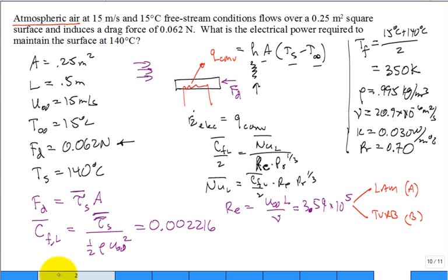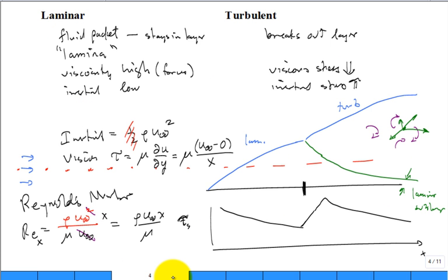So I know that I talked about this condition right here, but maybe I failed to emphasize something, but it's emphasized in the prerequisite course, right? What is the Reynolds number at which you would expect to have a transition between laminar and turbulent flow for flow over a flat plate? A lot of students will say one of two numbers. They'll say the critical Reynolds number for transition is either 2300 or 5 times 10 to the fifth.